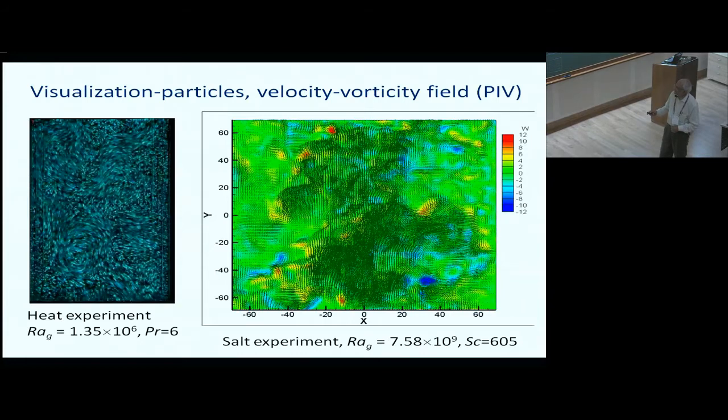And this is the PIV velocity-vorticity field. The vorticity is given by the color bar here, and you can see that you get very intense regions of vorticity, which is again characteristic of turbulent flows. And of course, the flow field itself is very random. You get very high velocities, for example, in this region at this instant of time. And you get all these random looking vortical structures. By taking a number of these PIV images, you can average them out to get the velocity fields.